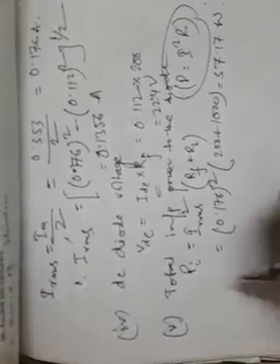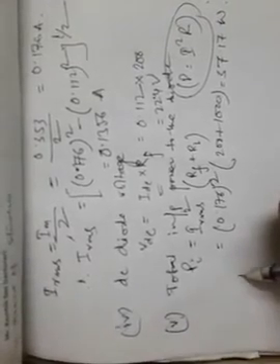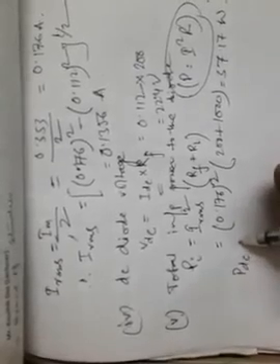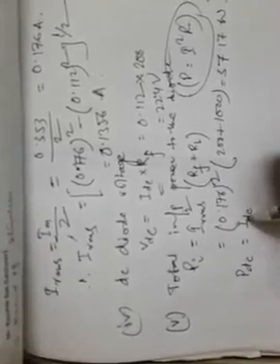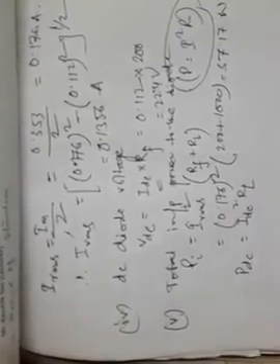Now if we want to calculate at the same time the output power also, that is PDC, we can also calculate. In that case we need to consider IDC and not IRMS, because the output of the diode will be DC primarily. So IDC square into RL, and that output flows into only the load resistance.